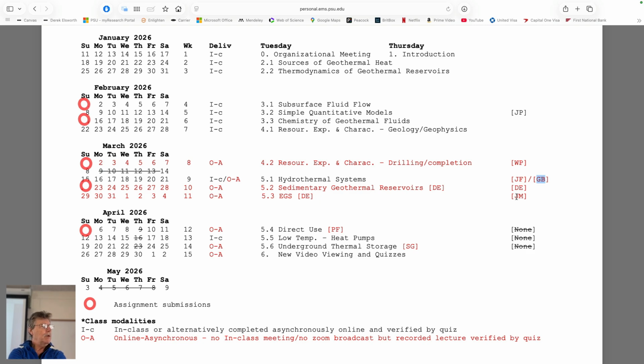Capital Energy. They work on small binary conversion units where you take low temperature fluids, less than the boiling point of water, and you put it through somewhere where you can vaporize a low boiling point fluid, such as isopentane, that will vaporize and run through a turbine in a closed cycle. And so you can generate electricity from units where the output of the geothermal reservoir is less than boiling.